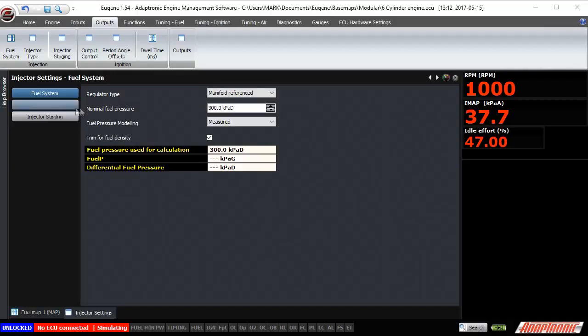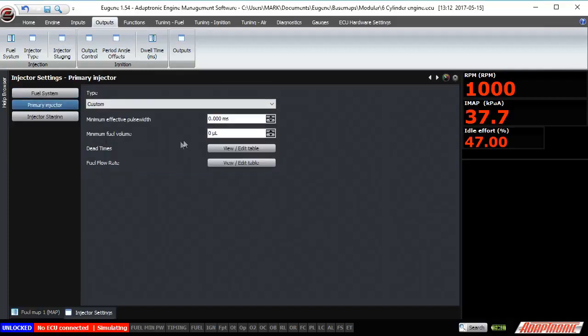So first of all, there's a minimum fuel volume setting that you can enable. And so in our previous example, we said that the injector wouldn't reliably deliver less than 25 microliters of fuel. If you set the minimum fuel volume to 25 microliters and the ECU is trying to deliver 10, for example, then it'll say, well, we know that we can't deliver 10 reliably, we'll just deliver 25, and it means that the engine's going to be too rich in that part of the map, but it's better than having the injector sometimes not open or spit and cause bad misfires and that sort of thing.